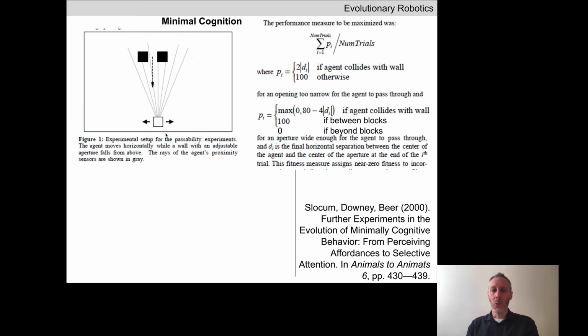Okay, so what are we going to do? We're going to evolve these CTRNNs, and I won't bring up the slide deck again, but you'll remember that this robot has a bunch of neurons inside. Each neuron is described by a differential equation. Each of those differential equations has a series of parameters associated with it. Each neuron has its own tau, its own gain, its own bias, and I'm probably missing one. It also has a set of weights, which are all of the weights of the synapses arriving at that neuron. So we're going to evolve all of those parameters.